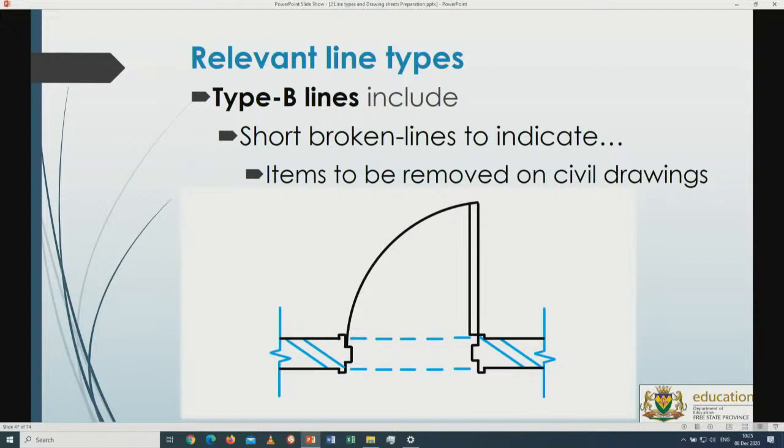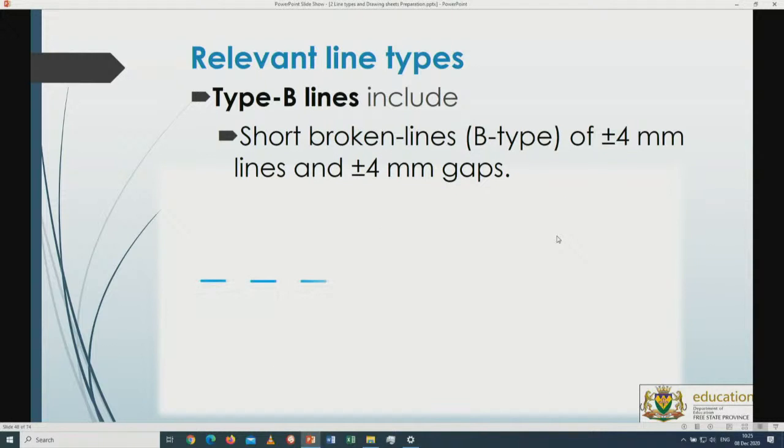Alright, now for everything that you're going to remove, in other words, you break down the wall, you build a door inside there, and then from there on it shows that once there was a wall, the wall has been broken off, there's a door now, so that is not as important anymore. So we take that out and we replace that by an opening, and then of course we do have your door swing and the door and the walls itself as dark lines. Right.